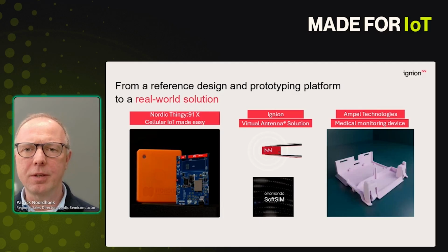Yeah, one way I understand what you're asking, I don't have the exact answer here. The other question I see here is that in rural areas, Cat-M signal is struggling. Does Nordic have plans to support Cat1? I assume Cat1 bis you mean here on this platform. Issue being here, Cat1 bis is a full duplex platform. The chip is not made for a full duplex solution. It adds a massive amount of complexity to both chip design and external filters. So it's not.